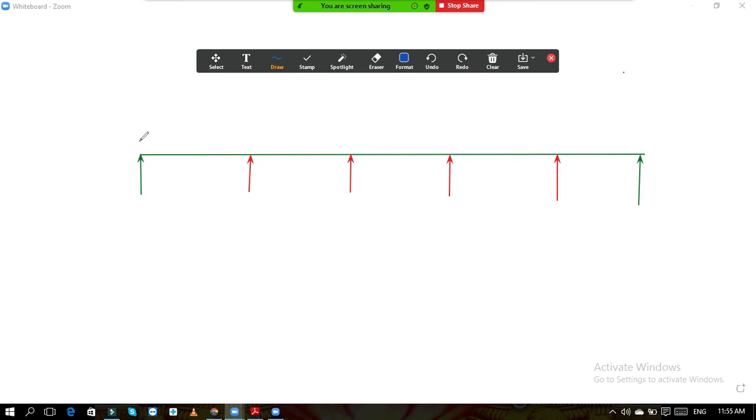then the bending moment diagram will be, here at the support some hogging moment will be there. Then at the center sagging moment is there. Again at this support hogging moment will be there. Again at the center sagging moment is there. Again hogging. So this type of bending moment curve you will get in the case of these continuous slabs.